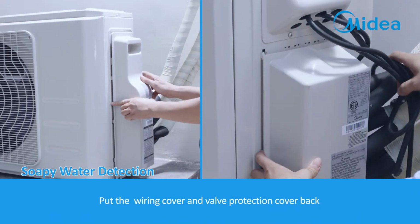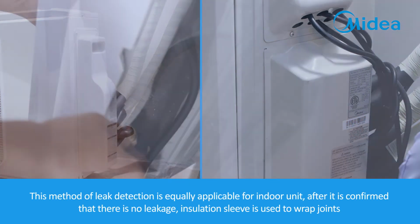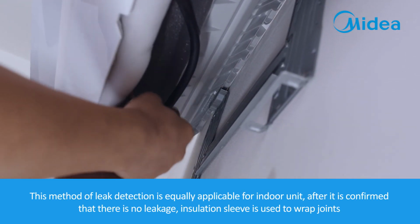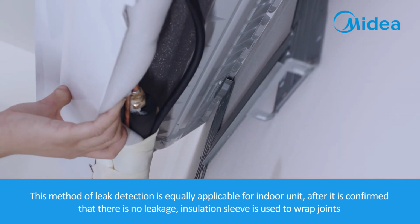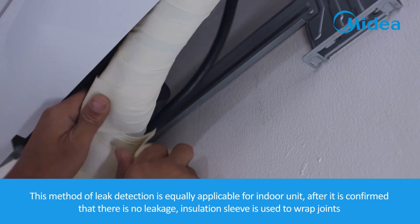Put the wiring cover and valve protection cover back. This method of leak detection is equally applicable for indoor unit. After it is confirmed that there is no leakage, insulation sleeve is used to wrap joints.